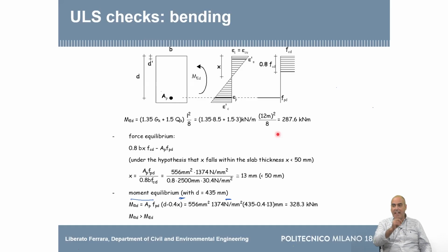We used to say planar cross-section equals linear strain diagram. Yes, that is true, only if your beam has a straight axis. If your beam has a curved axis, and you can have that in precast structures or timber structures, then planar cross-section does not mean planar linear strain. It means that the cross-section remains planar, but the strains are logarithmic and nonlinear. This is something very important that you have to take into account.